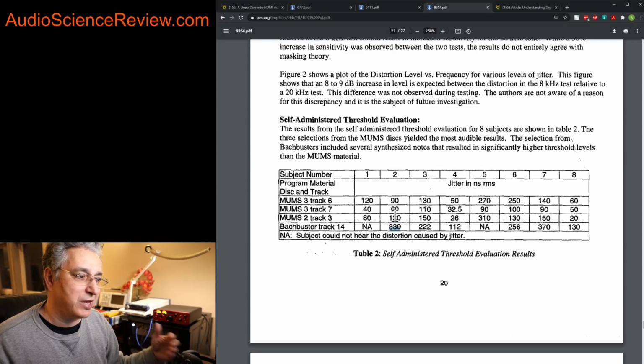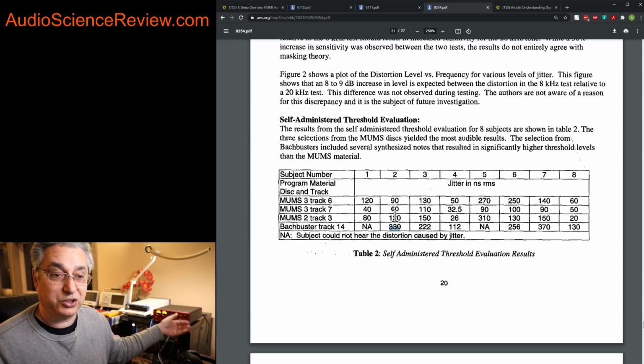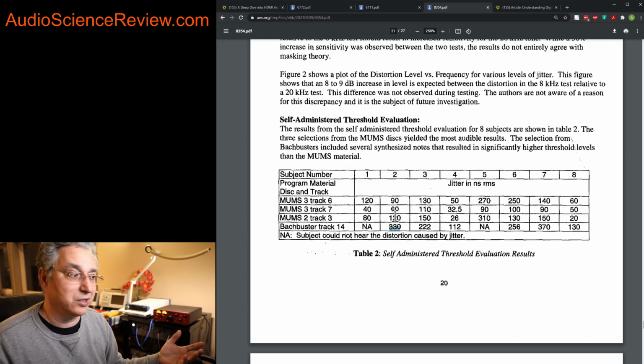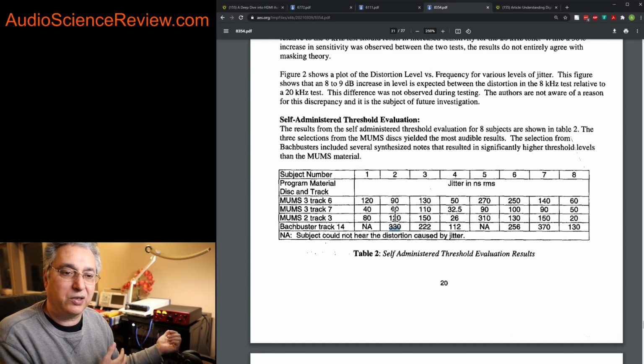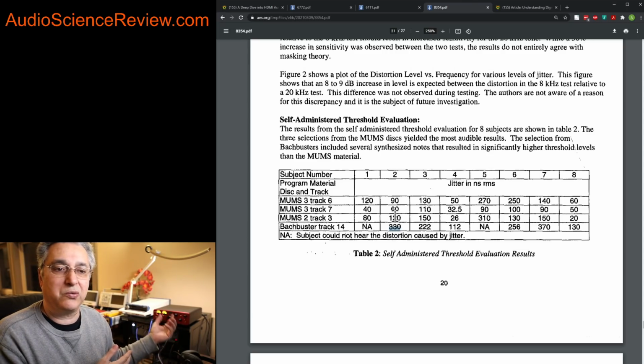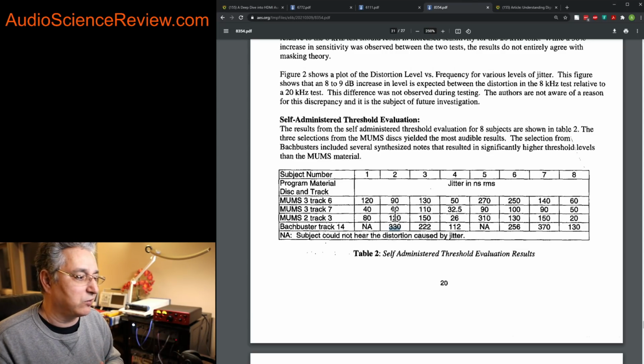That bothers me. So I measure it and I show it. We show it with this J-test signal that is supposed to aggravate the situation, but it doesn't literally cause any jitter. It's just a signal like any other digital data, and just happens to be specially made with a square wave that's rather clean. And we like to see a clean spectrum. I don't want to see a whole bunch of unwanted noise from the rest of the processor, or USB input, or a DSP in case of an AVR, what have you, bleeding into the DAC. It's a revealing test from that point of view.